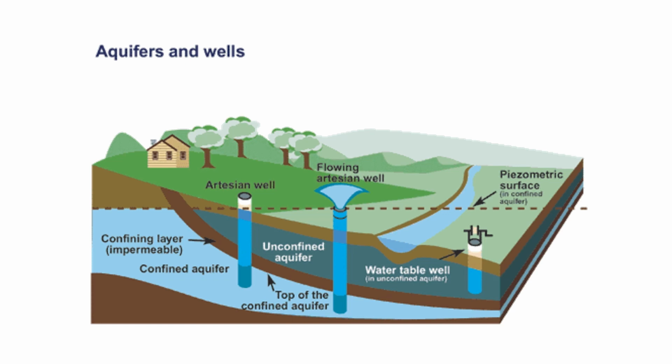Groundwater can be depleted if we use it at a faster rate than it can replenish itself. So wells can be drilled into the aquifers and water can be pumped out, but precipitation eventually adds water, sort of recharges water into the porous rock of the aquifer. The rate of recharge is not the same for all aquifers, though, and that has to be considered when you're pumping water from a well.